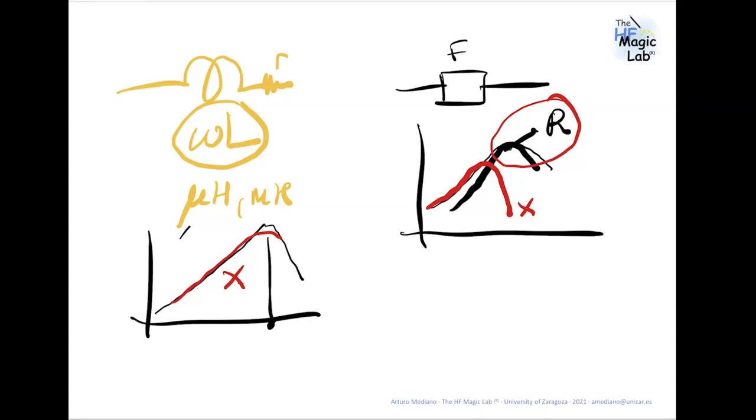What is the main reason to place the input filter on the opposite side of the power supply on the second board? Yes, this is what I answered before: in this way, you minimize the parasitic coupling between the DC-DC converter and the output filter. So the output filter is not detecting the magnetic field coming from the DC-DC converter. It's some kind of shielding. You are using the inner layers to separate both areas.